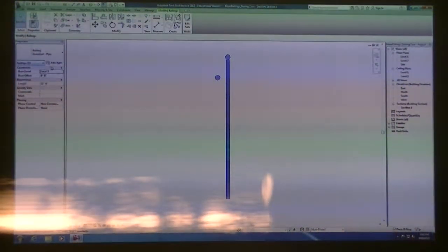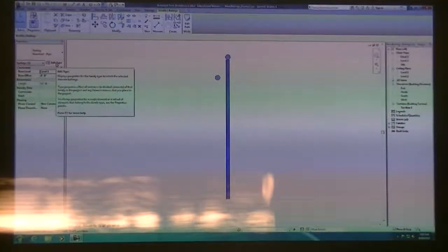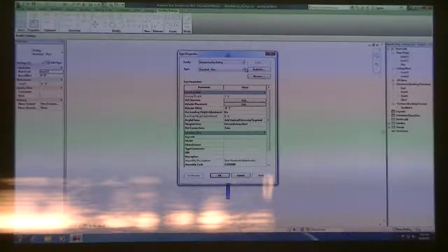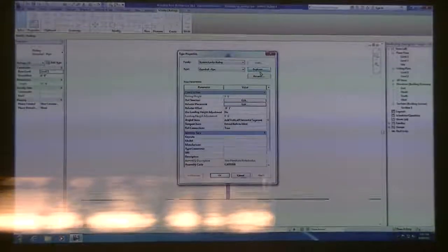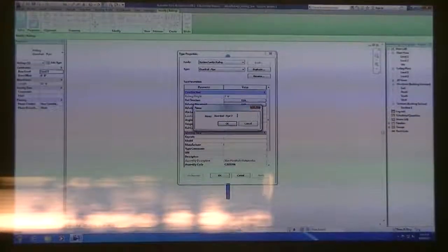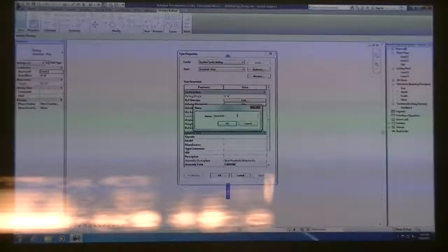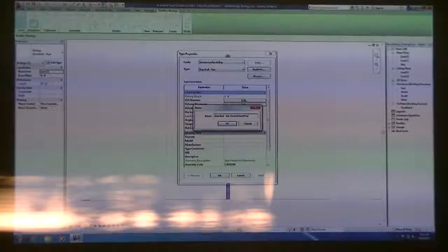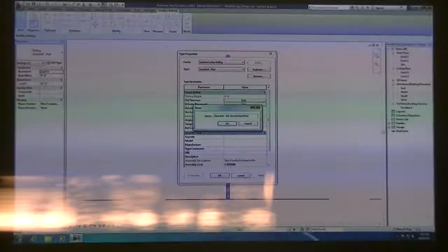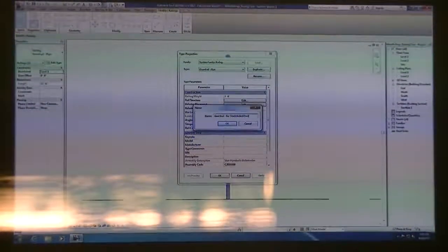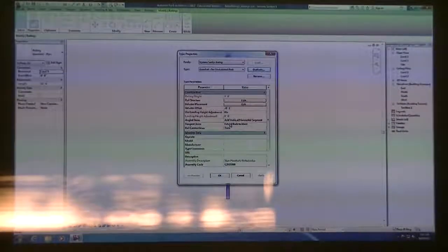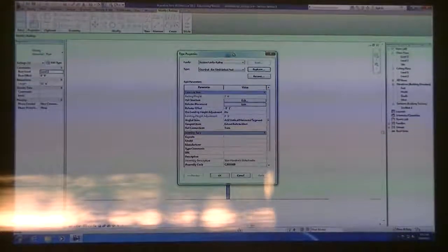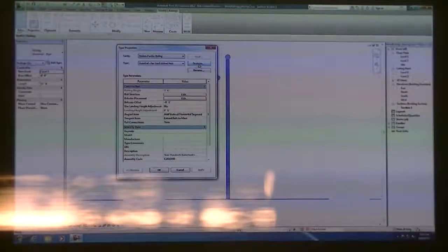And then once we click on this, we can click on Edit Type at the top left. And because we're editing something that already came with Revit, I want to duplicate this and customize it to give it its own name. So I'm going to call this guardrail bar stock kinked post. That I think will describe this handrail or guardrail system. Now click on OK. Did you duplicate that first, or did you? Yeah, just once you click on the railing, click on Edit Type, and then duplicate.